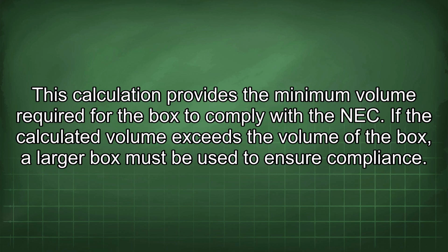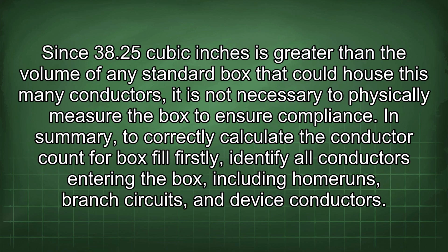If the calculated volume exceeds the volume of the box, a larger box must be used to ensure compliance. Since 38.25 cubic inches is greater than the volume of any standard box that could house this many conductors, it is not necessary to physically measure the box to ensure compliance.